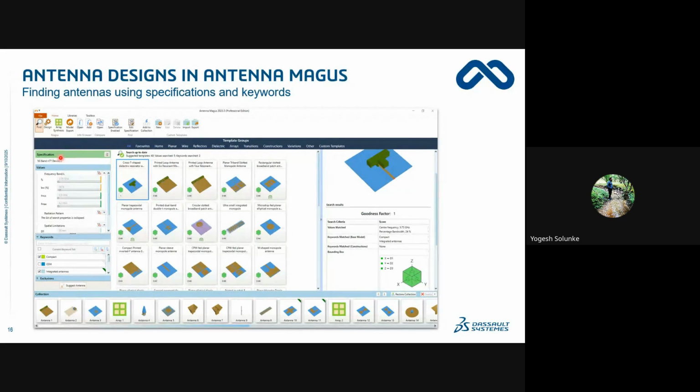What it asks you is whatever application you want to design, you need to select that. Let's say I want to work on the 5G band, so you can set up that 5G band. The second thing it asks is the operating frequency of the antenna. You need to give that input, and how much bandwidth there is. Once you set a percentage bandwidth, it will automatically calculate the minimum and maximum frequency. And some more inputs it will ask, like what dielectric material you need. Once you give those inputs, you will get about 15 to 20 different types of antennas which give you the same result as the inputs you have given. So this is a very smart way of designing, wherein you can get the structures, export them into CST, and if you want to do optimization, you can do it in CST also. So this is a synthesis tool.